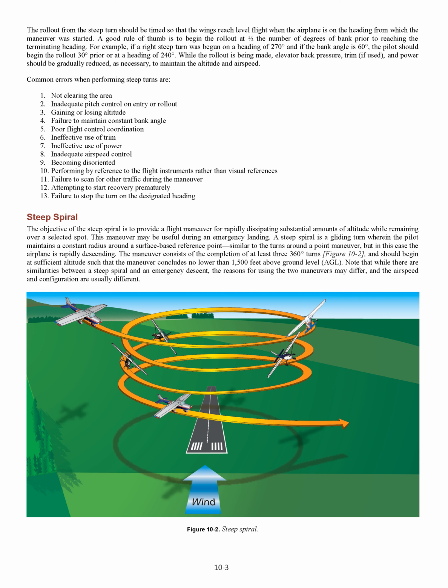Ineffective use of power. 8. Inadequate airspeed control. 9. Becoming disoriented. 10. Performing by reference to the flight instruments rather than visual references. 11. Failure to scan for other traffic during the maneuver. 12. Attempting to start recovery prematurely. 13. Failure to stop the turn on the designated heading.